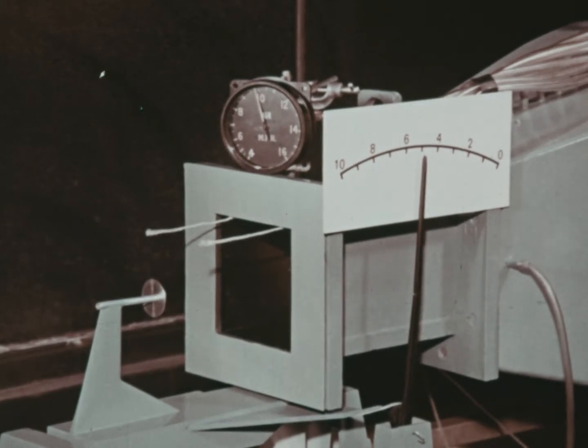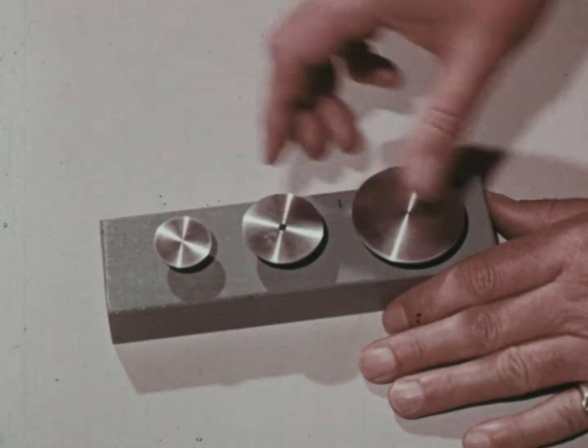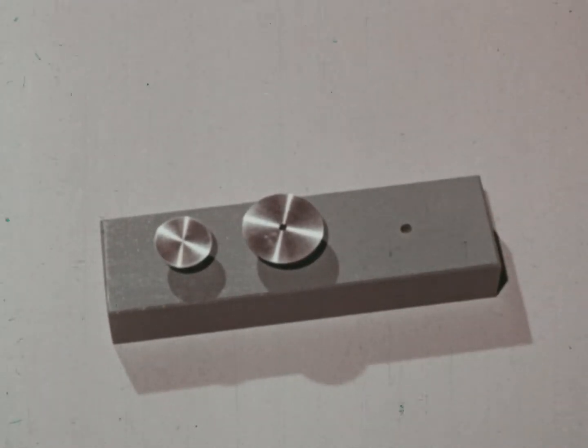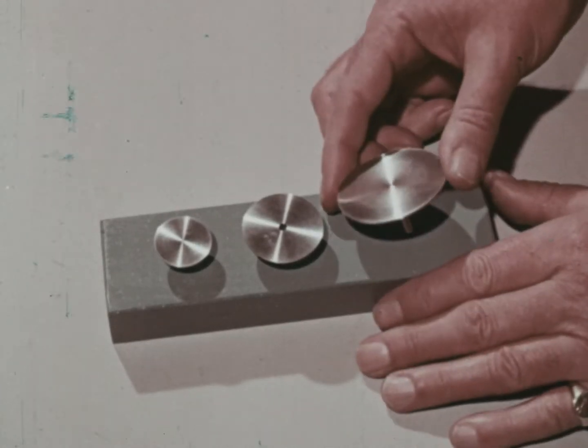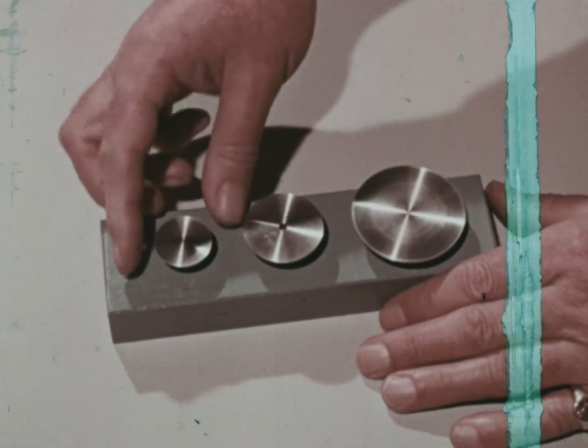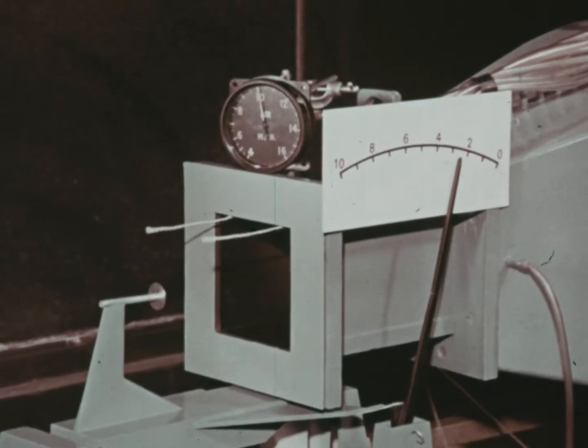With the airspeed indicator steady at 100 miles an hour, the drag on the disc records a value of 5 on the gauge. If we mount a disc double the area of the first, the drag gauge records a value of 10 at the same airspeed, double the drag. Finally, if we mount a disc only half the area of the first and a quarter of the area of the second, we get a reading of only 2.5 at the same airspeed.